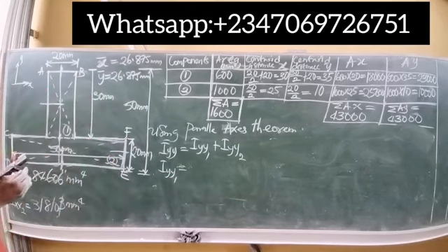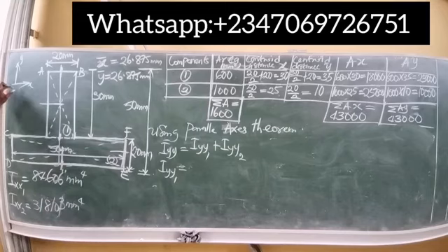The difference now is that when we did it for the x direction, we said x is our width, while y is our depth. Please take note. When we found the moment of inertia for the x coordinate, we said x is our width, meanwhile y is our depth. So if we are now looking for the moment of inertia for the y coordinate, take note: y is going to be your width, and x is now going to be your depth.